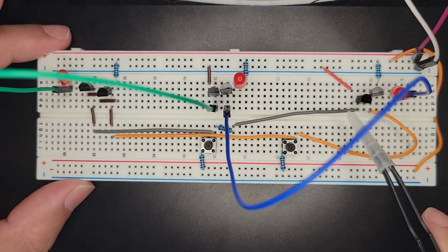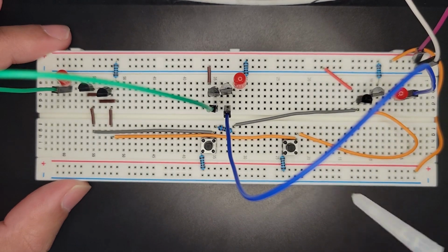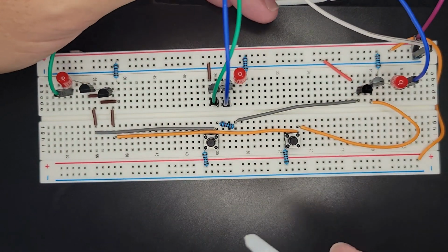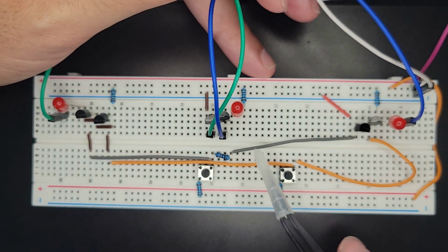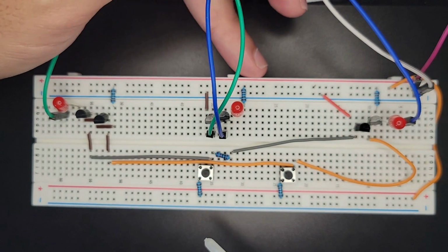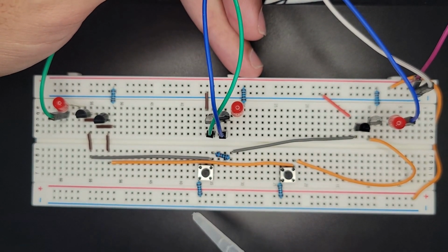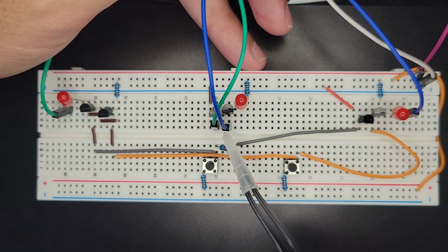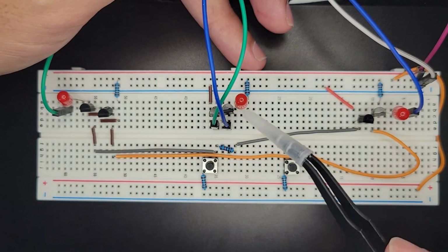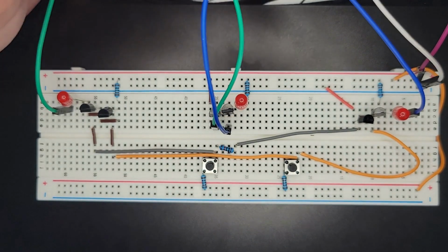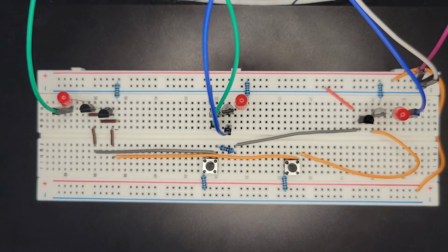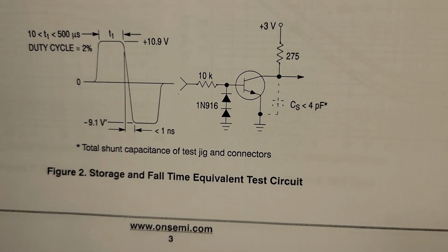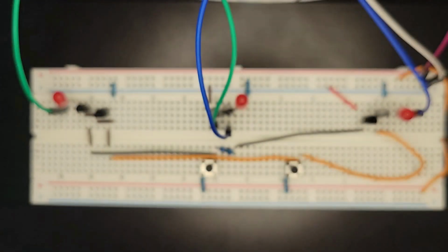These cables are super connected together. Sorry, the cable's in your face. So there's just way too much current flowing everywhere. I was so focused on voltage before. It's a current and it's a resistance. So what we need to do is add more resistors to the inputs of these bases, similar to what they have in the documents. So I'm just going to keep using 10Ks then from now on for my inputs to the bases and see if that fixes it.